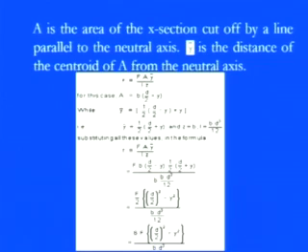So if you look at the parametric form, you will find that the shear stress for this kind of rectangular section depends on how the dimensions are varying. That means Y is always a varying distance, that is, how much depth you want to use, and what is the distance from the neutral axis to that strip. So that is the Y square, and D by 2 is the height we are using for our cross section, and then we have the BD cube. These are also the dimensional parameters of those things.